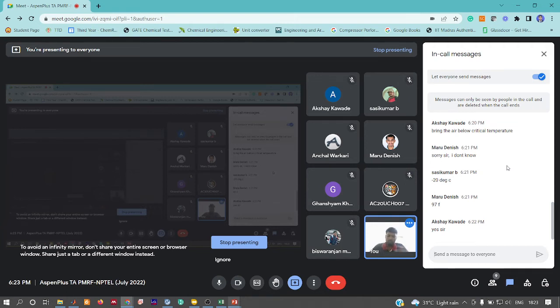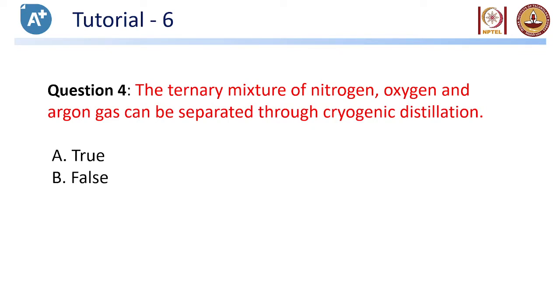What happens in cryogenic distillation is that nitrogen has a saturation temperature of 77 Kelvin at 1 atmosphere. Since it is 77 Kelvin, if our aim is to produce liquid nitrogen, then obviously we need to go further below 123 Kelvin. That's why it's called cryogenic distillation. It's the same fractionating column, the same simple distillation. However, since it is operated below 123 Kelvin, it's called cryogenic distillation.